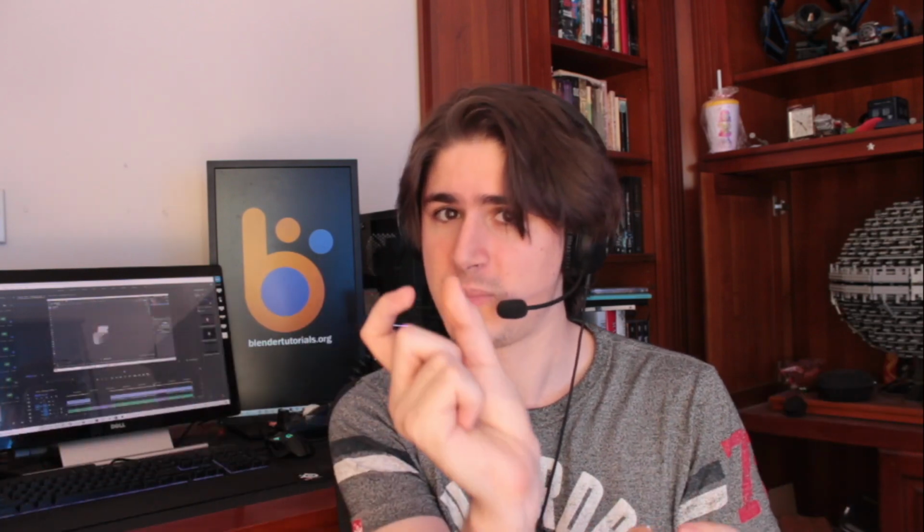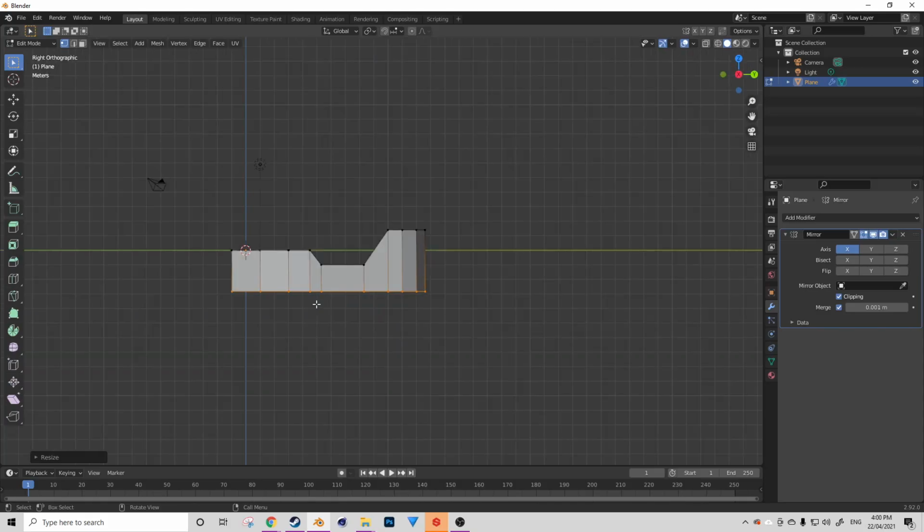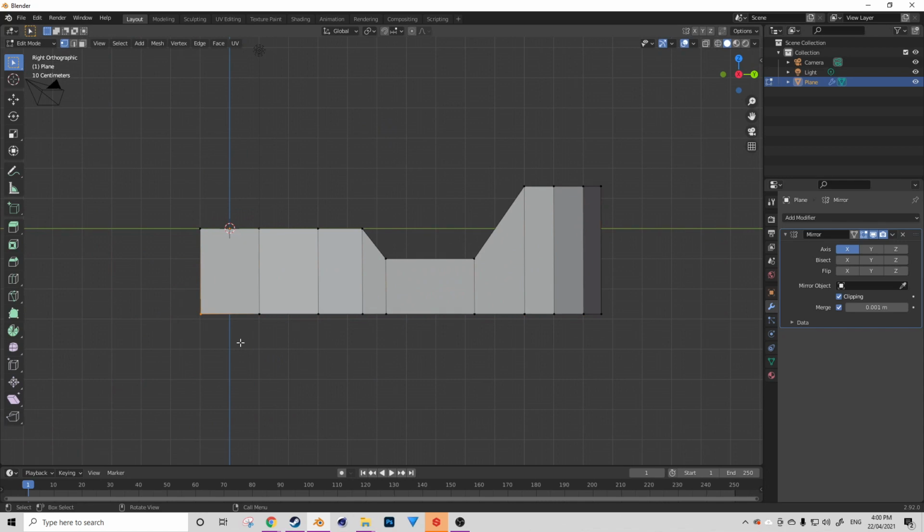So that's why when we select that entire bottom part of the ship, we have a median point that's between all those parts. And when we scale it on Z, we're essentially telling all those vertices, all your Z values have to equal 0, which is that median point. So whenever you want to flatten something in a certain direction, simply scale it in the direction that you want by 0. Now let's go into the side view and we're going to select the front part of the ship.